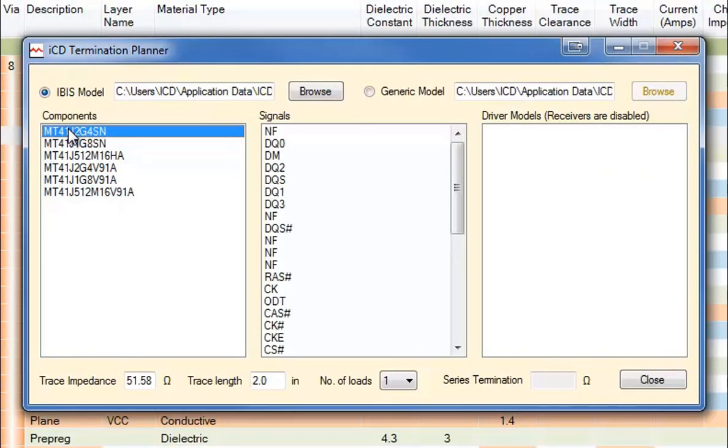any other model. Now, quite often you don't have the processor or FPGA model, simply because if you're developing the FPGA yourself, then you need to generate the model using the development tools. In that case, what you can do is use a micro memory model instead of the processor model, simply because the data bus is bidirectional. When it's writing, it drives from the processor into the memory, and when it's reading back from the memory, it goes back into the processor. So being the same technology, you can use the driver on either end, basically.